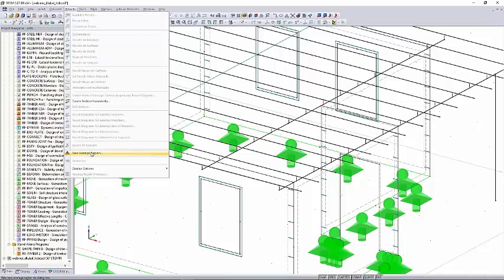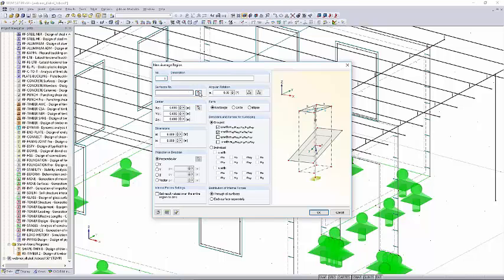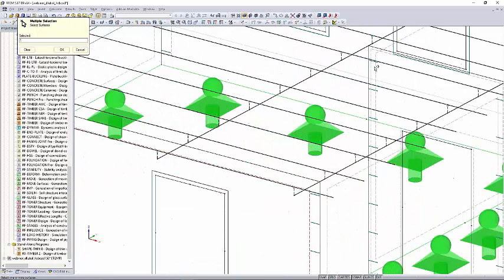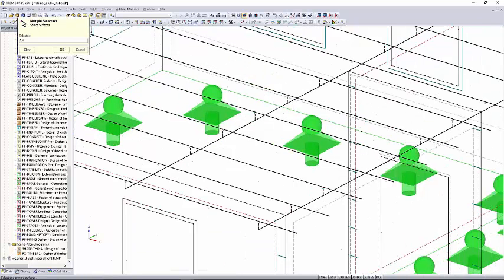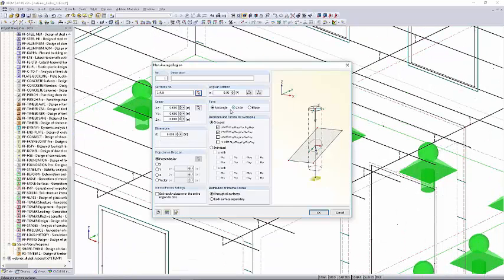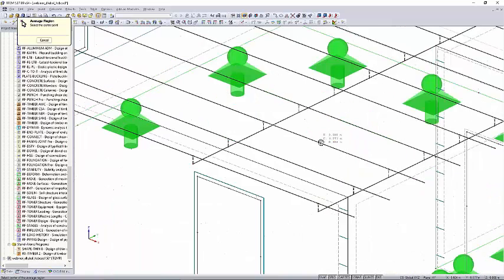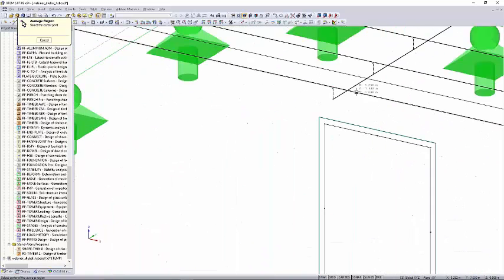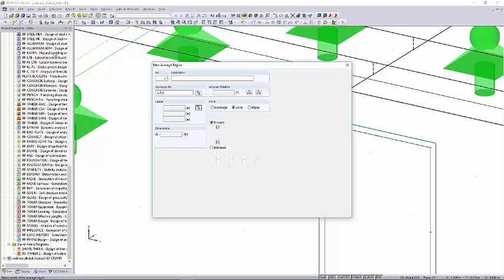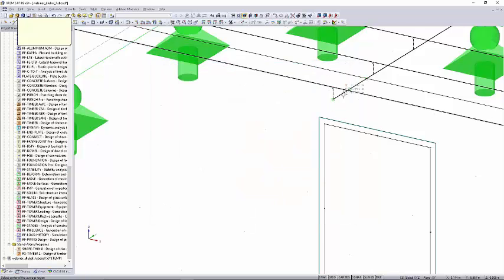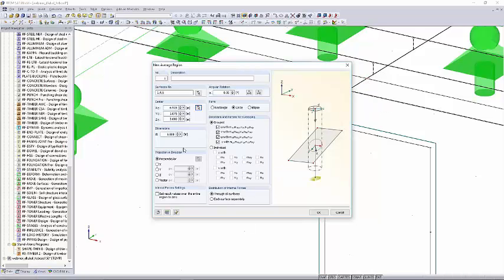Wire, hold on, results, average region, and it will go to this, and this surface. I use circle, and I will use a pretty big distance, like 1.80 meters, just to, I will tell you the reason later, just hold on, I will pick the node. Here you can see it already. I picked such a long distance because I will also have a singularity point here, and I will smooth all the results over this complete area. That's why I use such a pretty big distance. There, hold on. So that's what I wanted.